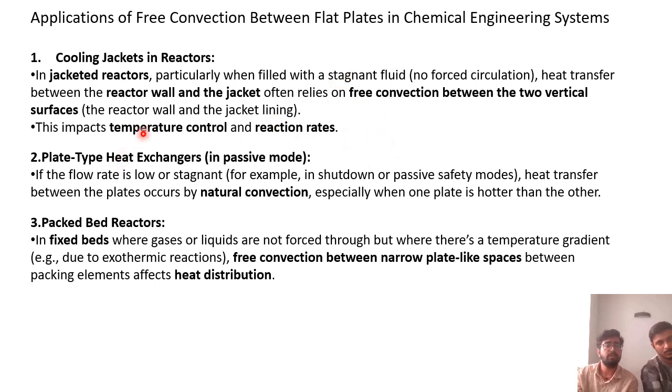So what happens is temperature control of the reaction, with this we can see. And one more important thing: suppose the pump is stopped, like some shutdown has happened, then we have to consider that the cooling jacket is conducting enough heat. So enough heat transfer is taking place even in the stagnant conditions so that overheating does not take place and it doesn't affect the reaction.